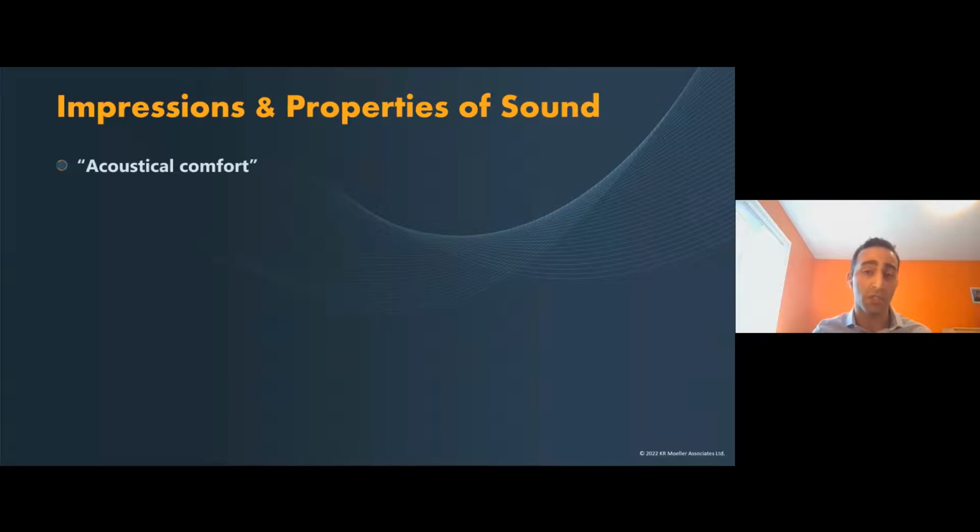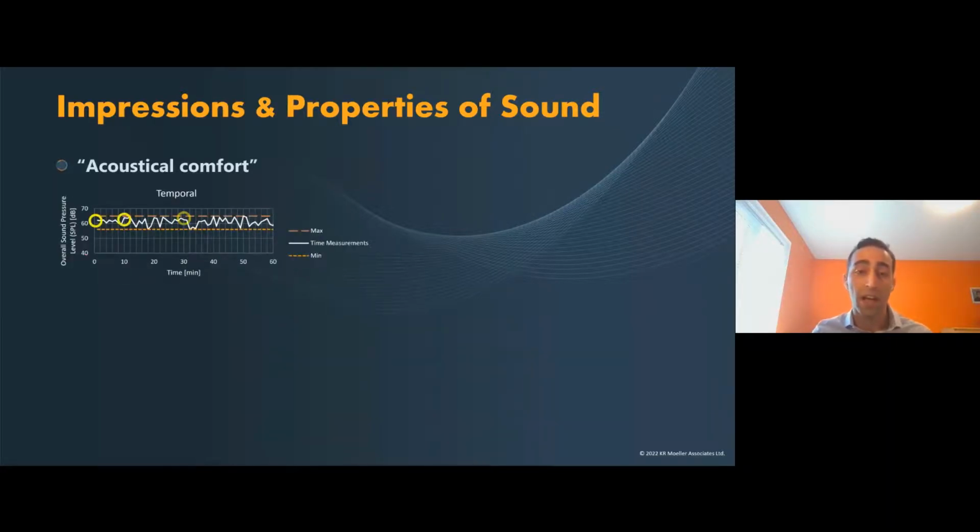To this point, we've considered 2 of the 3 dimensions, temporal and spectral characteristics of sound. The vast majority of acoustical work requires only use of this information. Yet the acoustic measurements produce vast amounts of data, and it's somewhat impractical to review it all. For this reason, we take averages of measurements with respect to time and spectrum. Our second graph on the right shows a snapshot of the 1, 10, 30, and 60-minute marks.